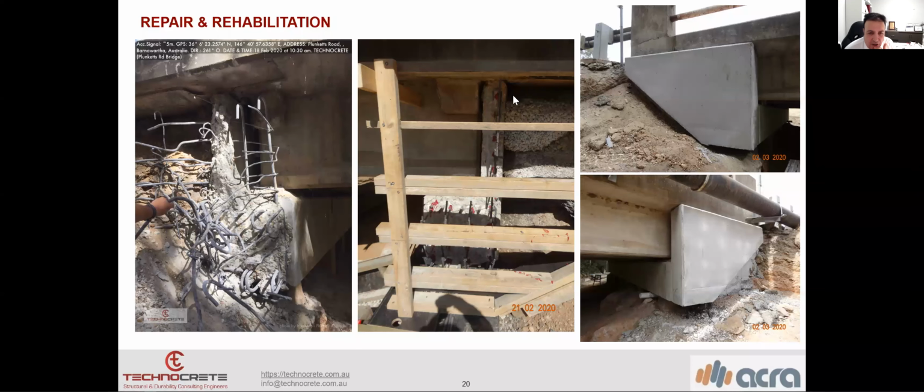With concrete spillways where dewatering is not feasible, which tests are recommended to diagnose internal issues? Is it a spillway of a dam, I think? Then in dam structures, the defects are a little bit more complex. I mean, we need more site information, but as a general thought, in water retaining structures like water tanks and dams, the first deterioration mechanism is the soft water attack.